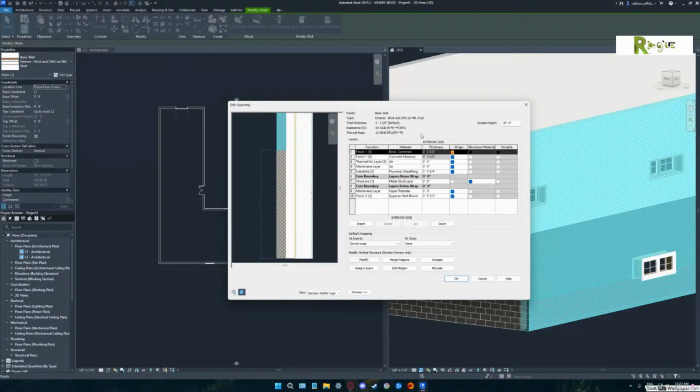You see where the merge regions button is? Yeah. Right above split region. Hit that. Okay. And then click on the line between the two regions. So hit merge regions. Yep. Click on that. There you go. Oh, okay.